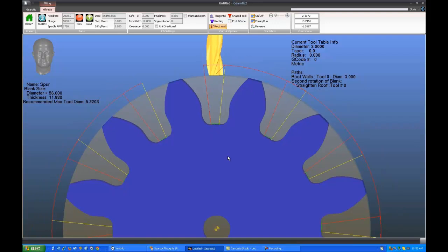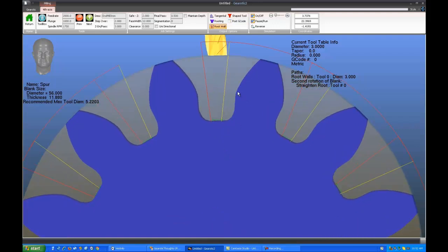That's not how it works in practice. Quite often we have trochoidal shapes, such as on the screen here. However, it should always be safe to place a cutting tool on an angle from the edge of this junction of the involute with the base circle to the root, and it tends to clear up any material which might have been left by a rooting step.